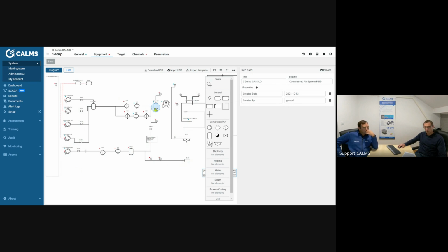And another one, when we opened the drain in this receiver, it was full of water. So obviously you have some problem with the dryers as well. So when we walk through, we identify a few problems. So maybe it's best to go through the list, through the questionnaire, prepare all the documentation, and then we will decide if it makes sense to do the measurements, the audits, or you think the easiest way is to buy a new compressor which will deliver 8 bar or even more.